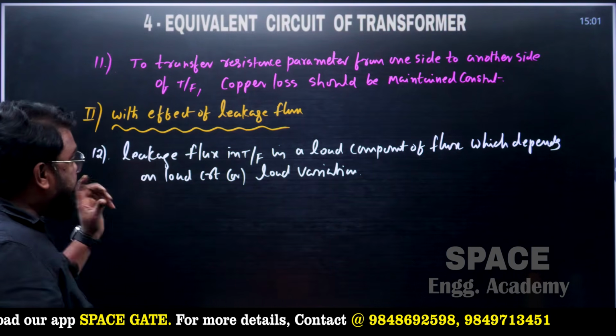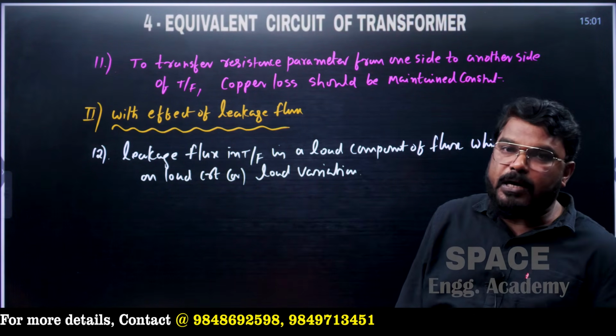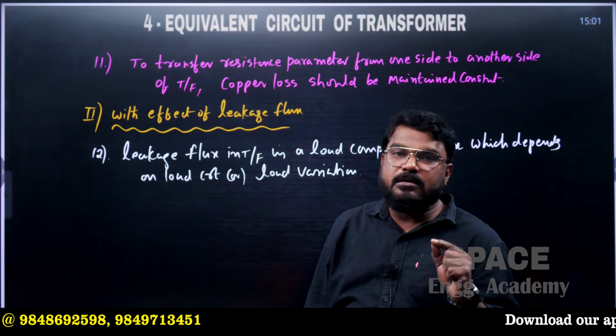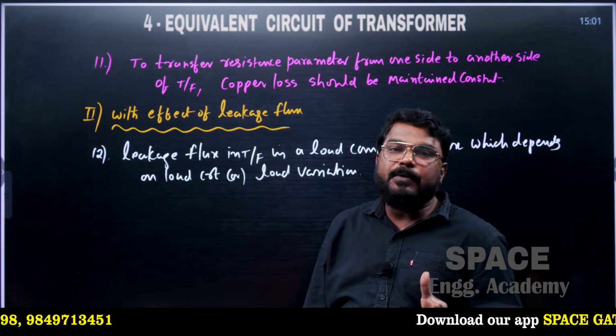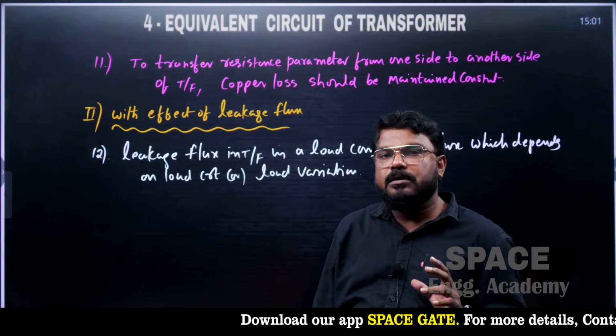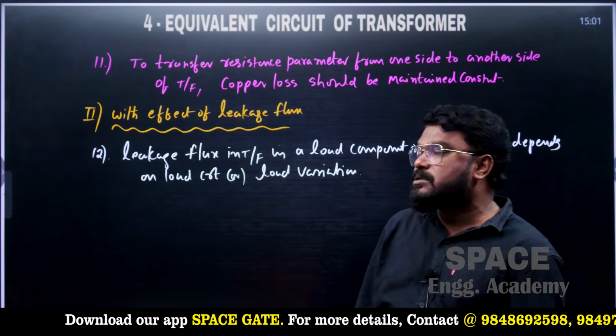And how do we model the leakage flux in a transformer? Leakage flux creates some voltage drop but not any power loss. That's why it is modeled with an inductive reactance element.